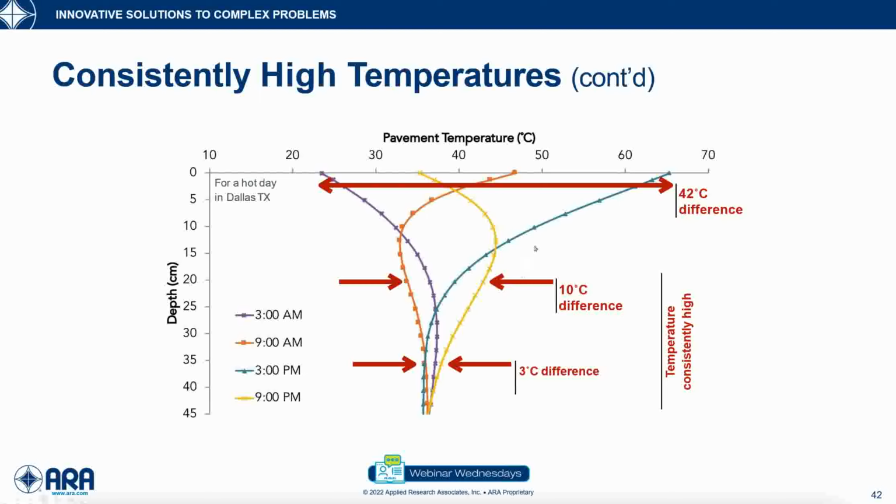Of course, it's not as high as the surface layer, but at the surface, that hot temperature is only applied for a short period of time, shorter than in the base layer. So the base layer is feeling high temperature. Again, that high temperature is making it softer. So I have three effects now: gear type, speed, and temperature, all contributing to softness in the base layer.